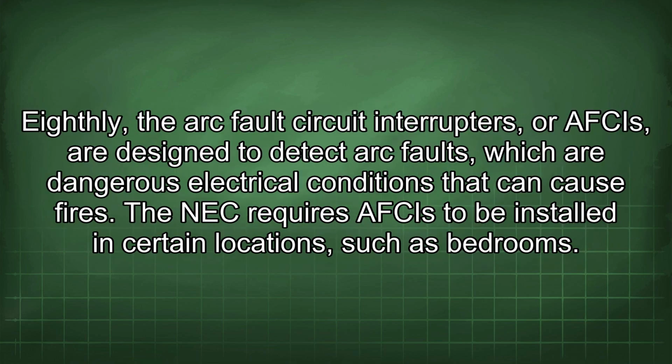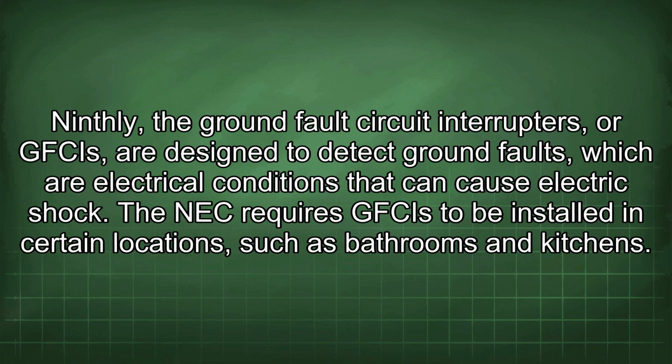Eighthly, the arc fault circuit interrupters, or AFCIs, are designed to detect arc faults, which are dangerous electrical conditions that can cause fires. The NEC requires AFCIs to be installed in certain locations, such as bedrooms. Ninthly, the ground fault circuit interrupters, or GFCIs, are designed to detect ground faults, which are electrical conditions that can cause electric shock. The NEC requires GFCIs to be installed in certain locations, such as bathrooms and kitchens.